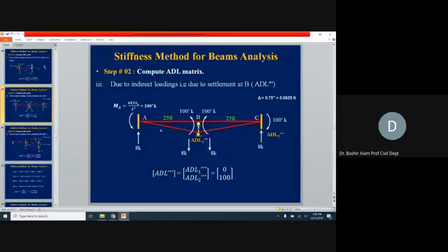The balancing couple is now simple. Here for the left span, the BA span, if you take 100 plus 100, so 200 is the unbalanced moment. Now we need to balance it by a couple, so this is divided by 25, the span being 25. So 200 divided by 25 is 8. You see here now, the unbalanced moment was in the counterclockwise direction.